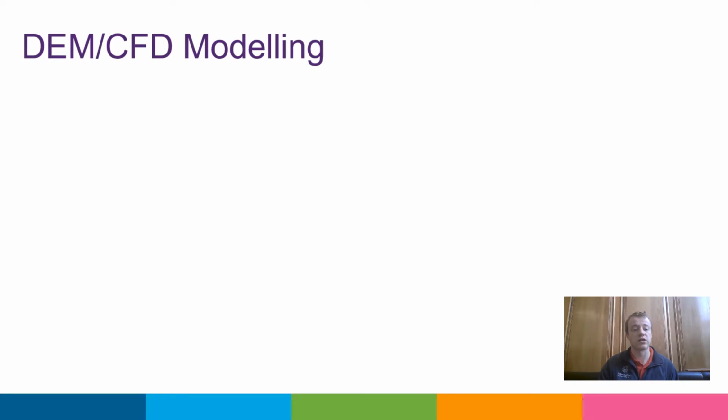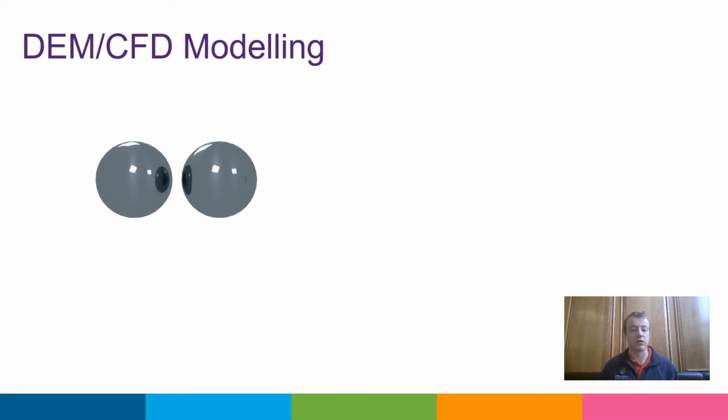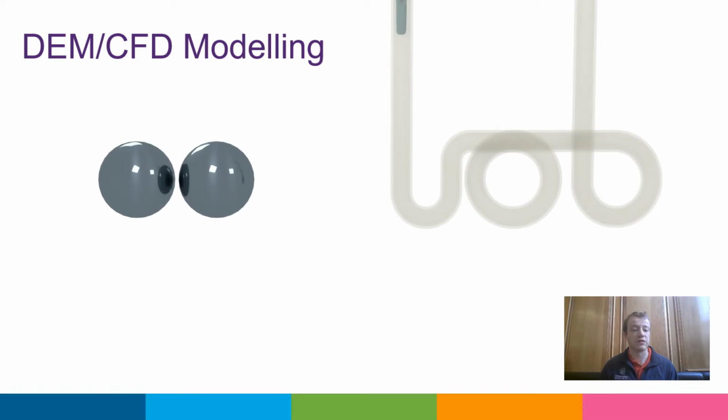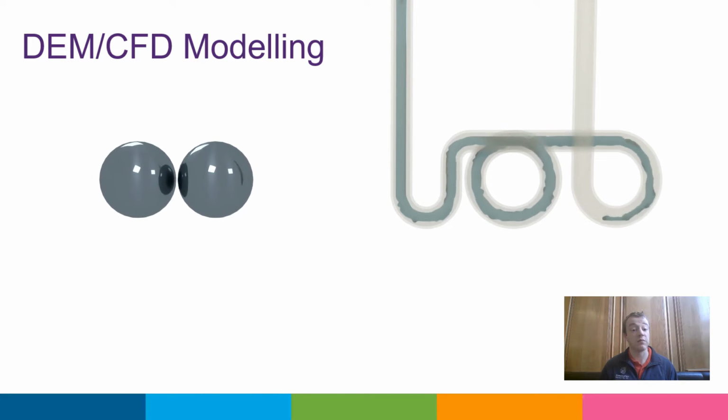So how is my research tackling this issue? What we are aiming to create is a calibrated model which simulates the behaviour of the milling performance. We are using a coupled approach of two techniques: the discrete element method, DEM, which was invented by Cundall and Strack, and concerns the motion and interactions of the grinding media beads, and computational fluid dynamics, CFD, to simulate the slurry phase, which is a derivation of the Navier-Stokes equation. The particulate material is assumed to be part of the CFD fluid, as the individual particles are simply too small